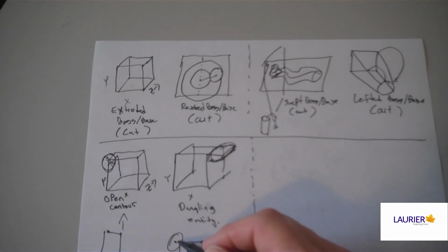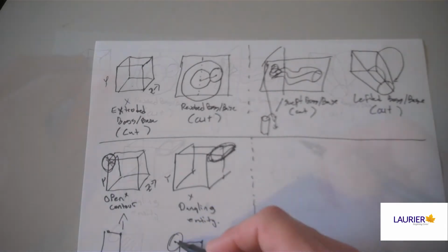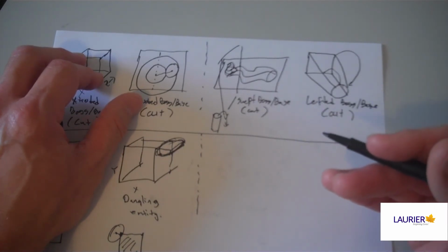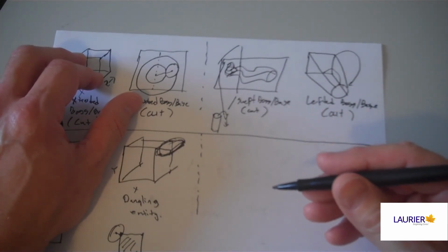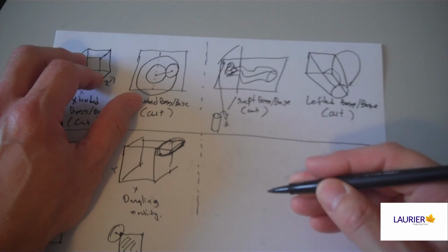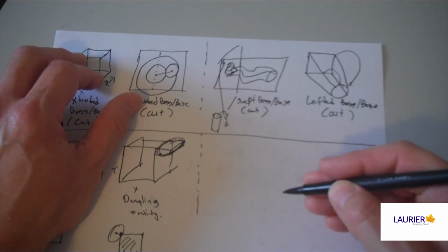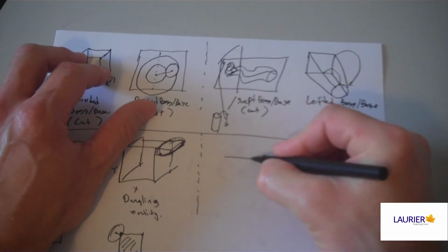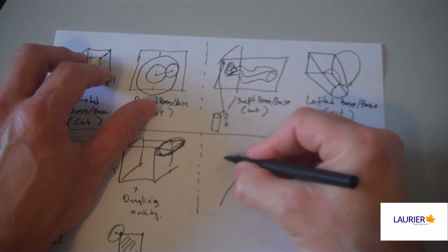To fix the problem, you simply delete the extraneous line. Okay, so that covers the two volume-related errors that can come up. The remaining two errors have to do with trying to share a line or a point between two different solid objects. In the first case, we've got, say, a closed X shape like this.